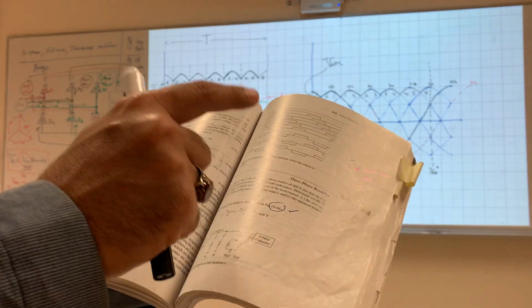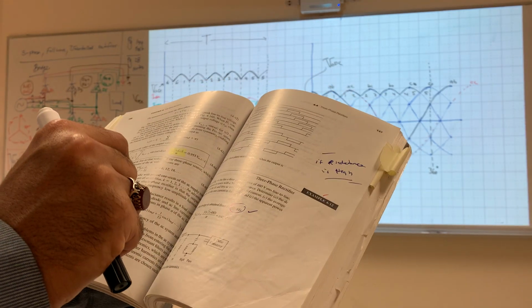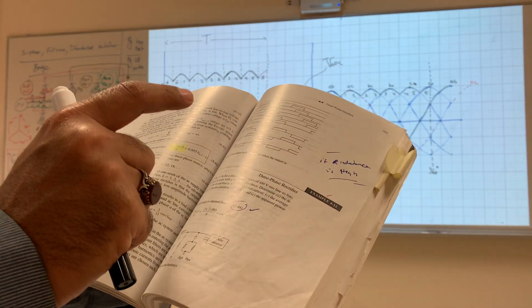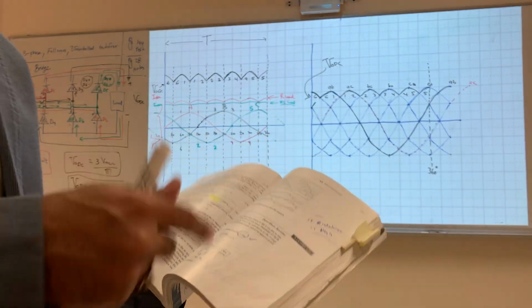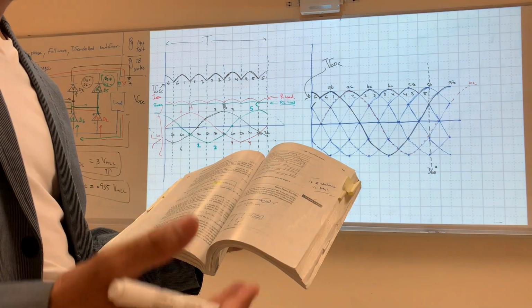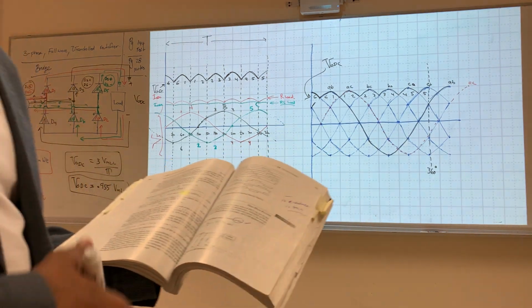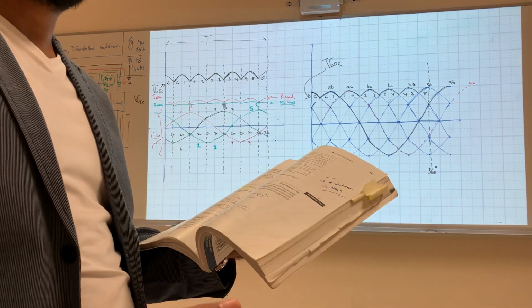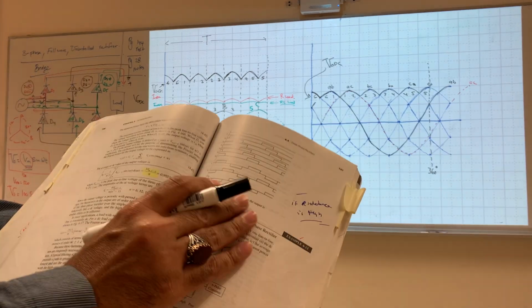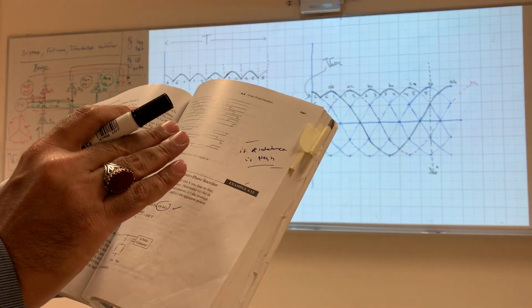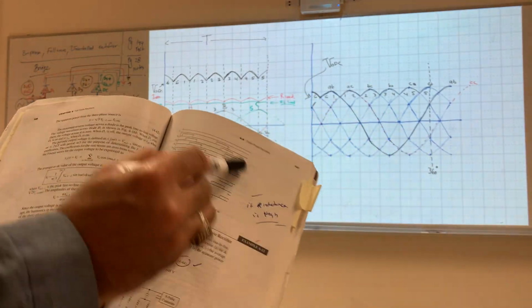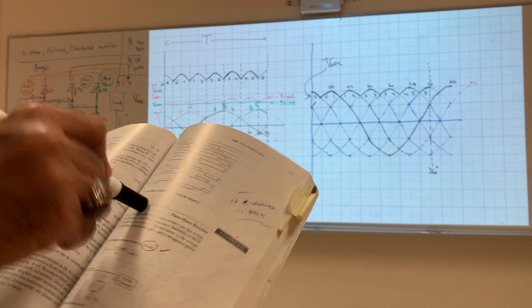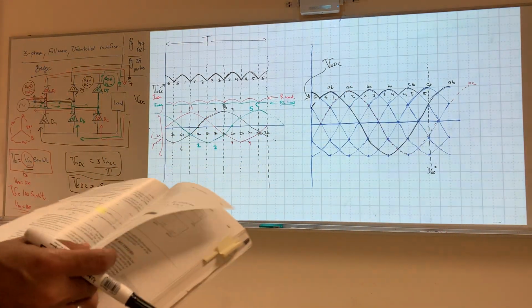And I told you before, if you want a straight DC, you will make the inductance huge or infinity. So when you filter the output current, you need huge inductance. And if you want to filter the output voltage, you need a huge capacitance. So here we have high inductance as a load, and that's what we get straight. So to get straight DC current, you need huge inductance.